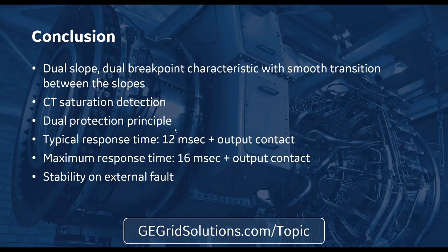So troubleshooting is very difficult, if not impossible, with a bus scheme without disconnecting CTs. Exactly. It's very difficult to troubleshoot high impedance bus differential. Plus, CTs have to be the same. The beauty of low impedance bus differential is all the CTs come in individually, so you can see exactly what's going on.